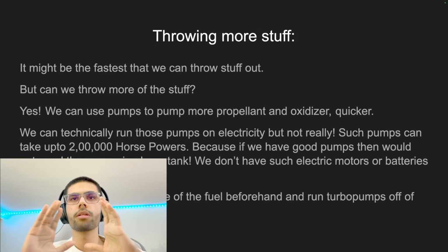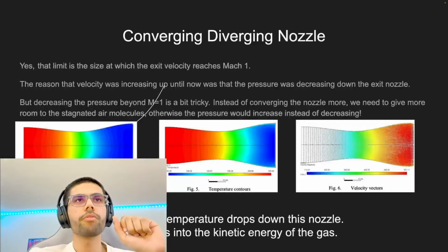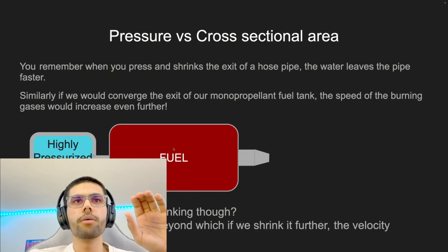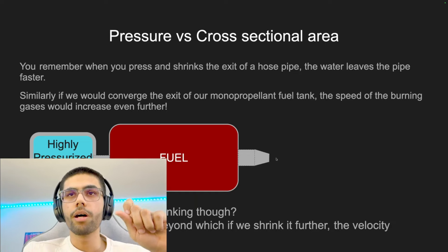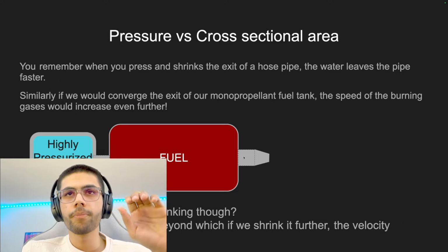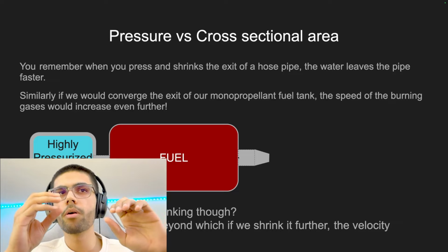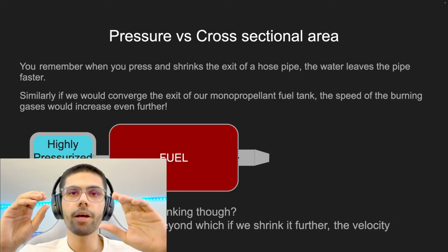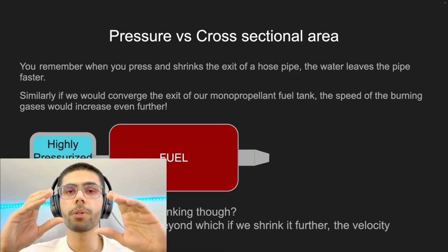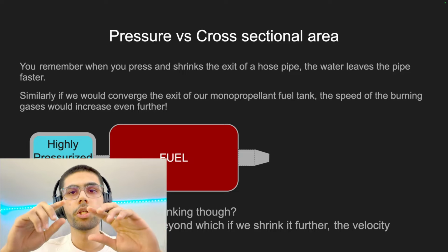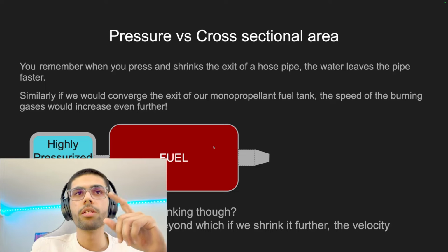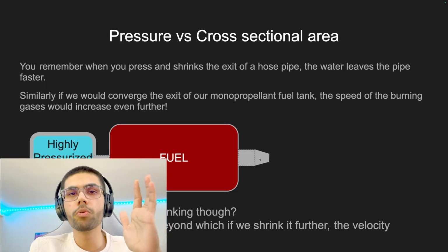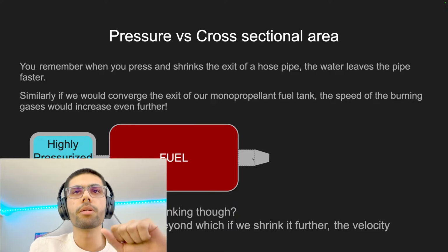Now, imagine for a second that instead of directly burning your fuel here and producing the high velocity gases over here, you first burn some amount of your fuel, and with the high speed gases generated over there, you spin your turbine, and that turbine in turn pumps more fuel to your main combustion chamber.